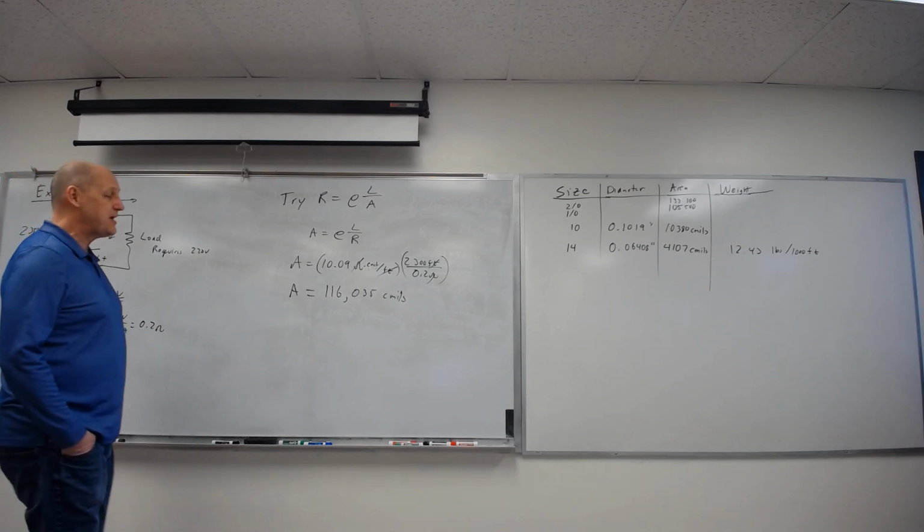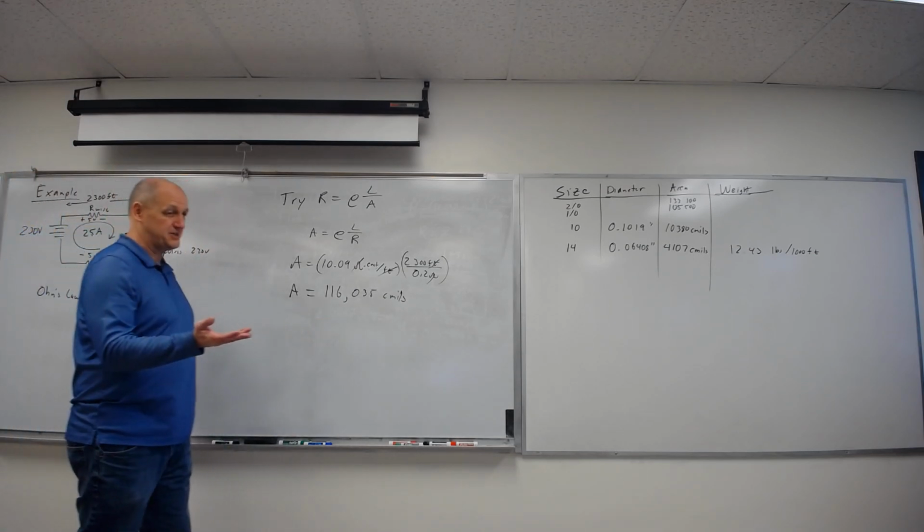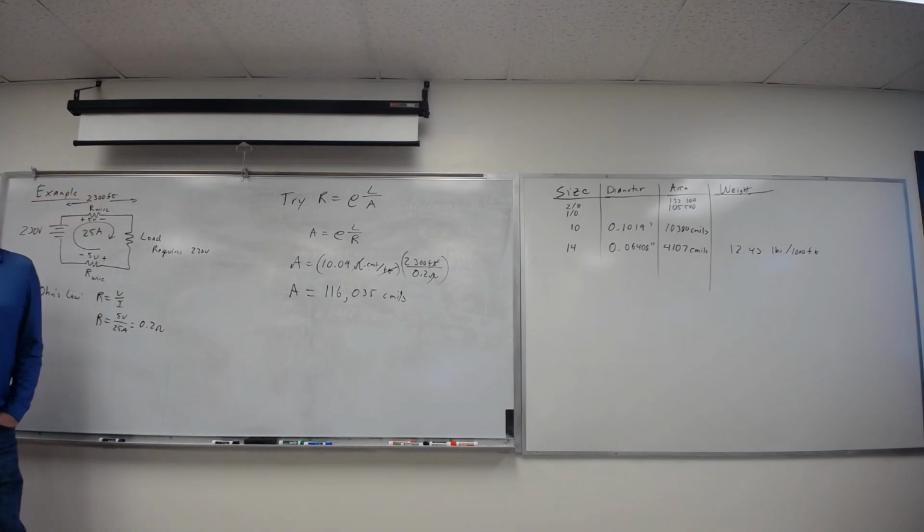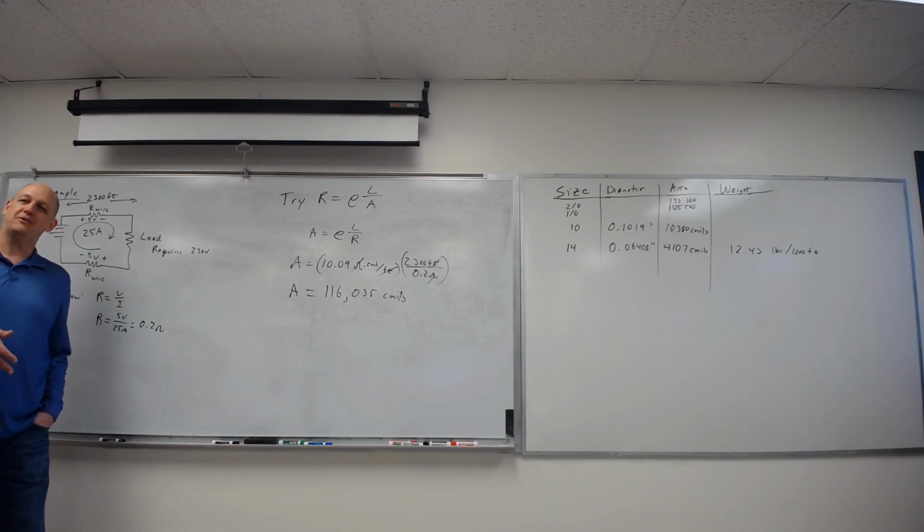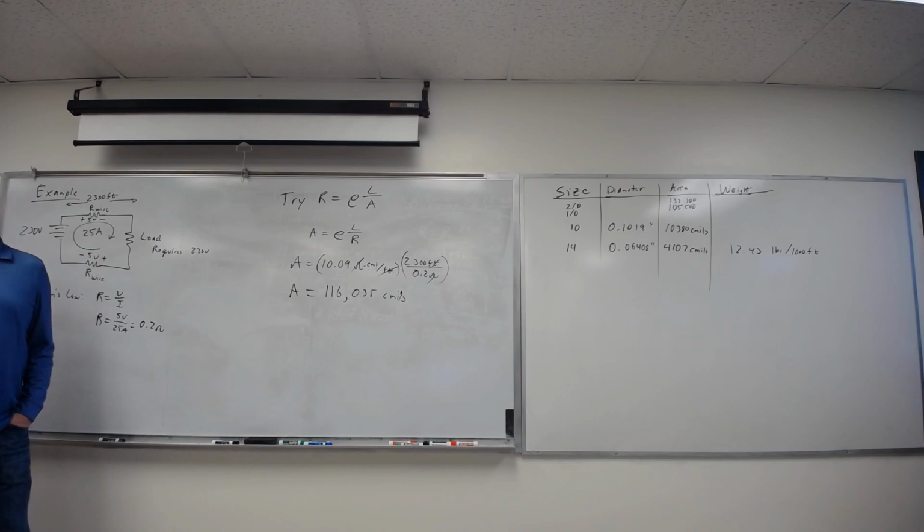So yeah, at the end of the day, we use copper because it's a very good conductor, but it's also one of the, I don't want to say it's one of the best, but it's one of the good conductors that's not super expensive. But it's also physically tough, but not so physically tough that we can't work with it. If you did solid steel conductors everywhere, not only does it not conduct quite as well as copper, but it's a lot harder. If you had a 14 gauge copper wire, you can bend it with your hands pretty easily. If it was a 14 gauge steel wire, you would need a pair of pliers and two hands and a lot of patience.